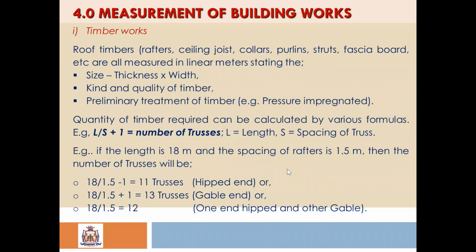If the roof is hipped end, then you get that length, you divide by the spacing, you subtract 1. That is the hipped end.